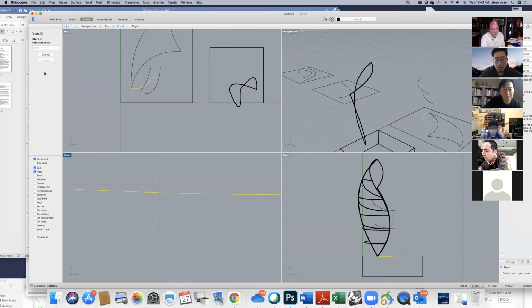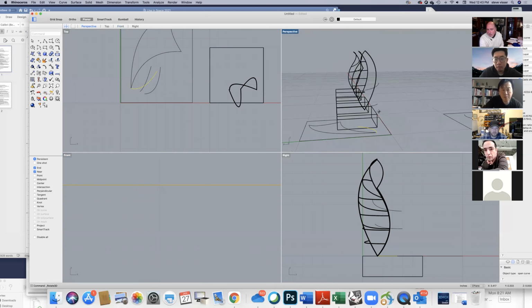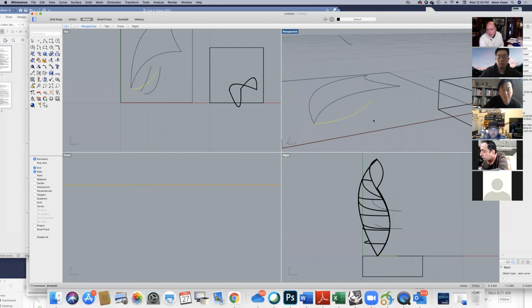So I'll right click on rotate. I need to pick the endpoint, the other endpoint, a point that's along the arc somewhere near, and then hold Shift to get it to lay flat. So now I have rotated that three-dimensionally to be flat on my paper without changing the shape of it.